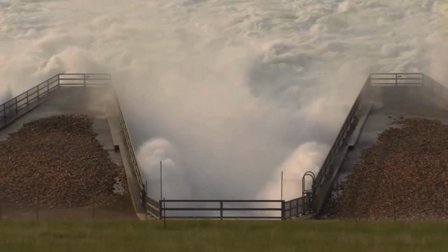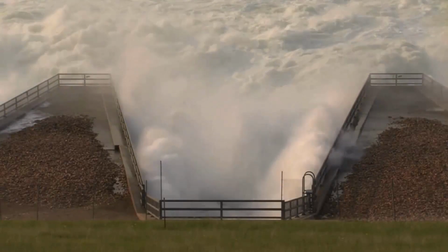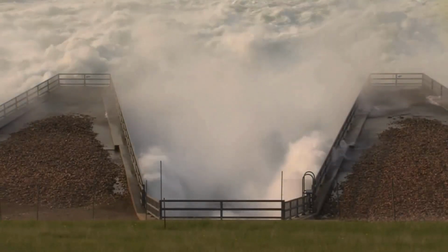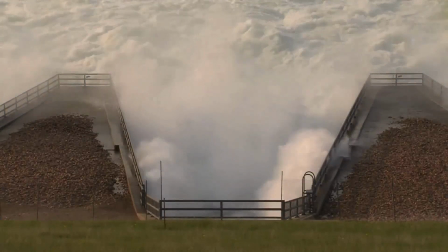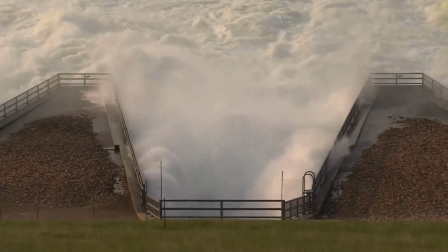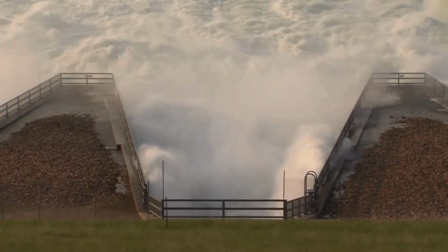I just erased our number. You're going to need that later. 18,333 CFS per pipe. We've said already that Q equals V times A. We used that formula when we were talking about Bernoulli's equation, where we had some pipe that's changing diameter and we have fast-moving velocity when there's a narrow diameter and slow-moving velocity when the diameter gets bigger.